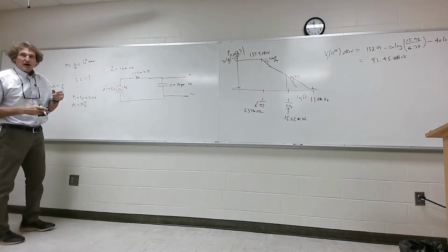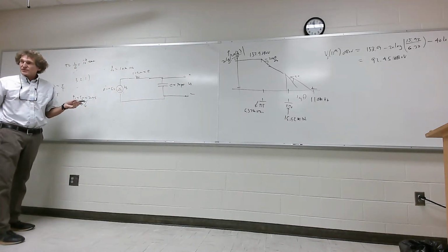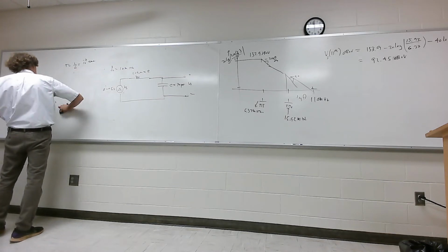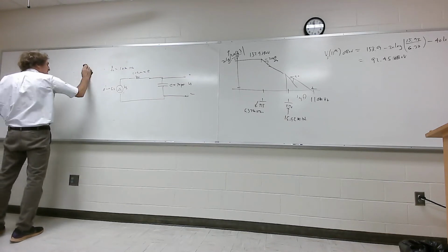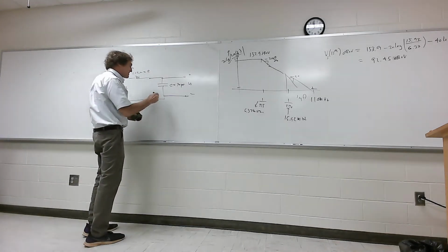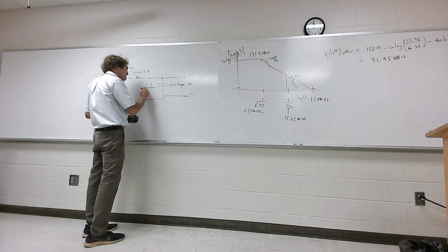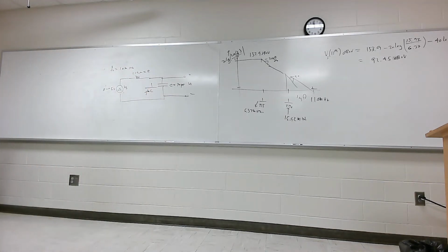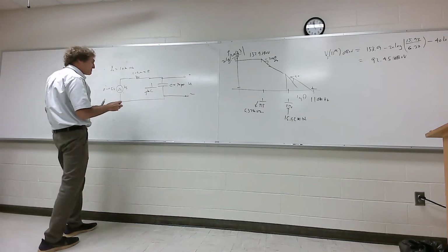We want the ratio of output to input. That is called the transfer function of a circuit. Y'all hear me, class? It's always the output over the input, whatever it may be, voltage, current, doesn't matter. So now I come over here, and I say, in general, for a circuit like this, you work in the impedance domain. The impedance of a capacitor is 1 over J omega C, correct? We're at discrete frequencies. Specifically, we care about the frequency of 110 megahertz. Y'all hear me on that? So we evaluate this capacitor of reactance at 110 megahertz.